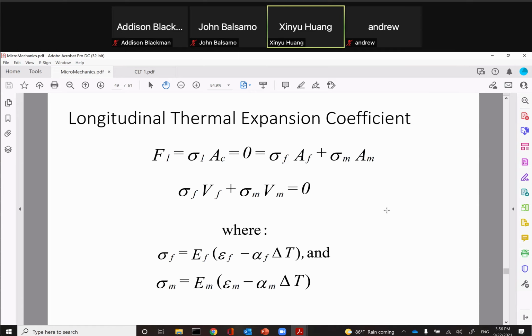Just imagine that you put two different metals together, copper versus whatever. You bond them together, you put heat on it. There's no external load, but the thing will actually bend, because they're fighting each other. One wants to extend more than the other. Okay. What if you want to design something with two materials that doesn't bend? You make it symmetric: copper, aluminum, copper. But there's still stress in there. The fact that they shrink, they fight, they didn't bend because it's symmetric.